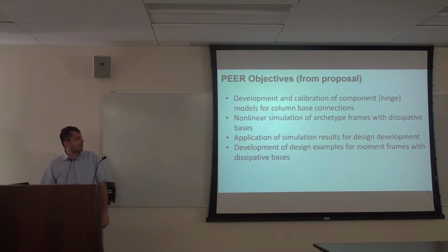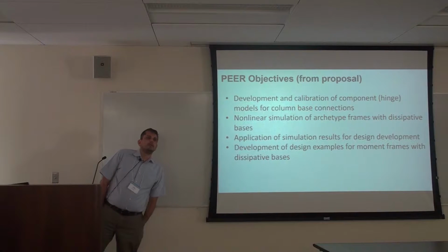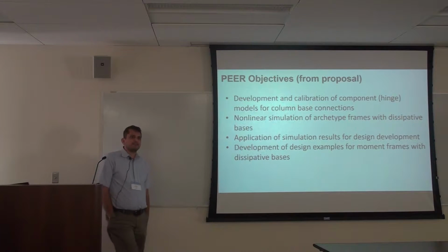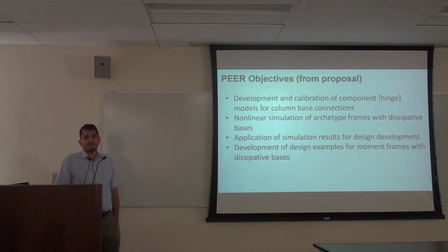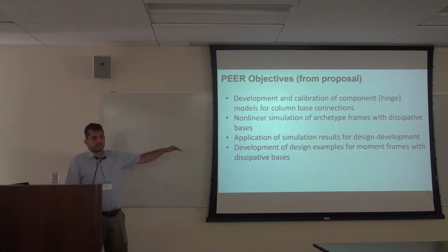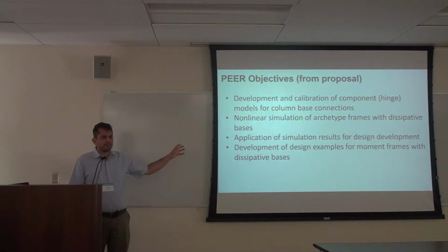We wanted to develop and calibrate component hinge models for column-based connections. And then we wanted to start doing some nonlinear simulations of archetype frames with these dissipative bases, to see what the relationships or trade-offs are between the column-based properties and the design decisions we make. Then start transitioning from there into coming up with solid design guidelines, and then developing design examples and so forth.